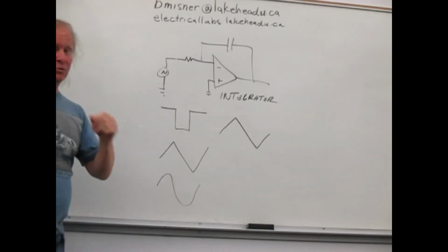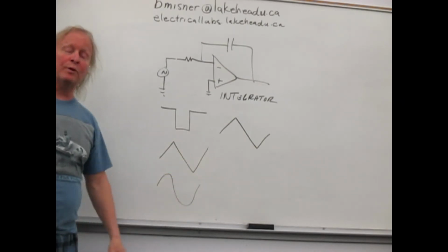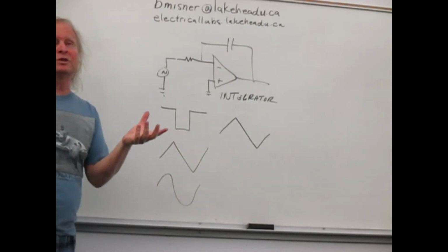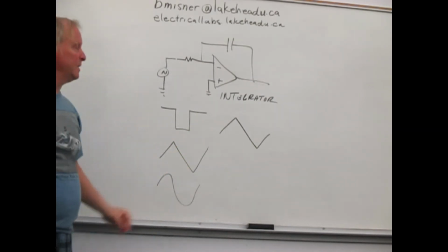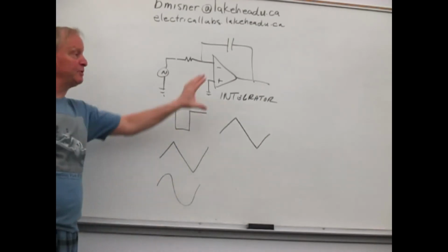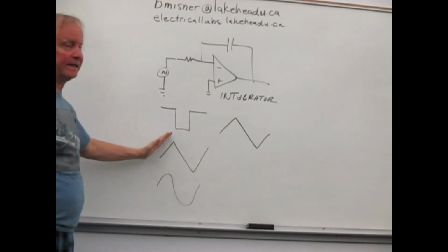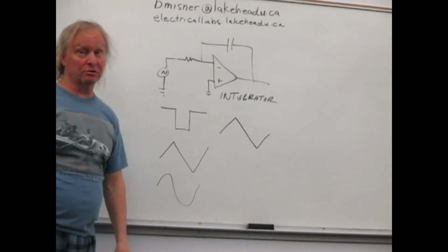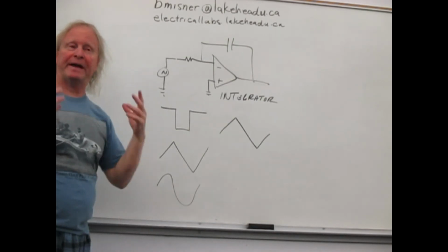One of the other things you can do is change the shape of the waveform. So when you use your function generator, or say you needed a certain shape of waveform, you can create these different shapes using circuits like this. Now when we look at the triangle, this is mx plus b. So the integral of that is going to be x squared, like parabolic.